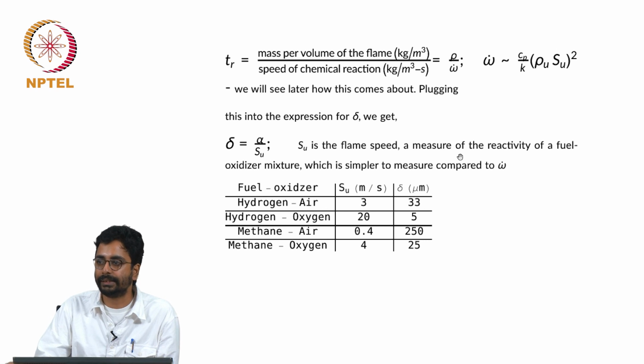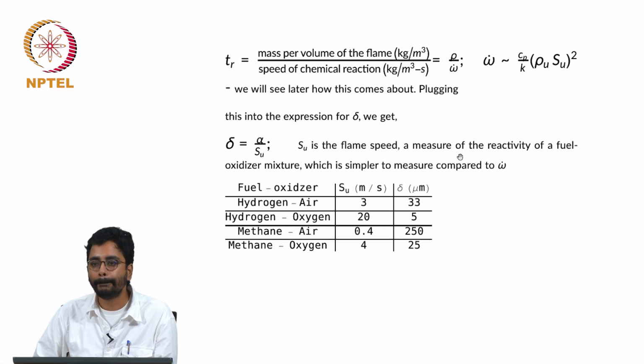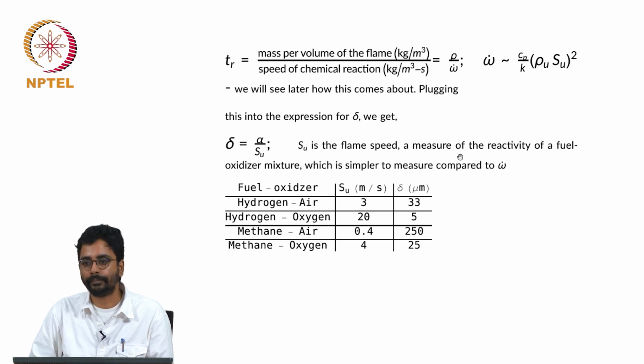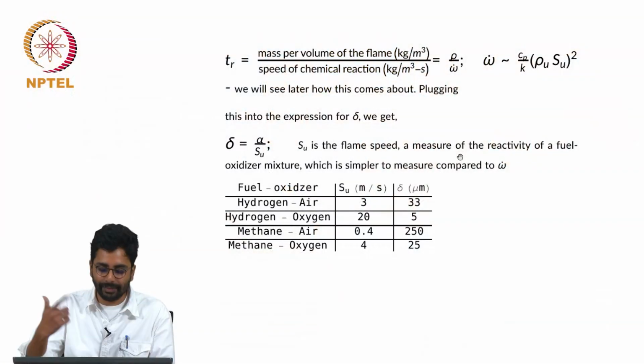Any other questions? Yes. We have been discussing flame thickness, which essentially involves the diffusion of heat and the diffusion of species into the flame zone. Where does the turbulence interaction come into the picture? And the assumption of delta n over n, where we are talking about the number of molecules entering and exiting the control volume, is that if the turbulent length scales are comparable to that, then our assumption is not taking that into account. Anyway, we will have a detailed discussion on this.